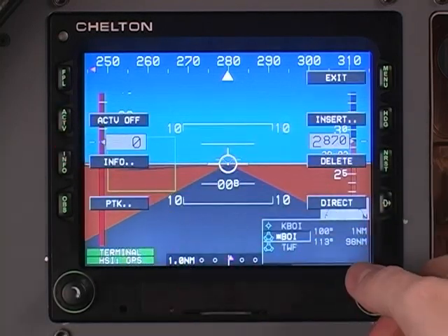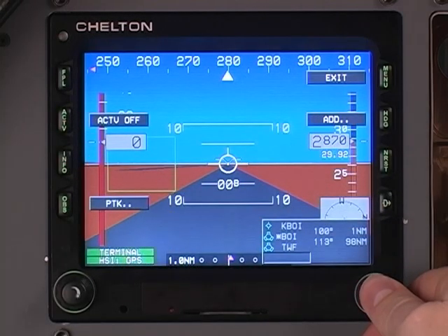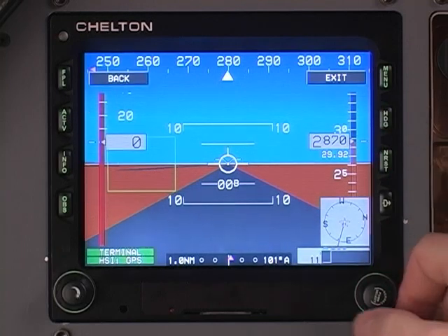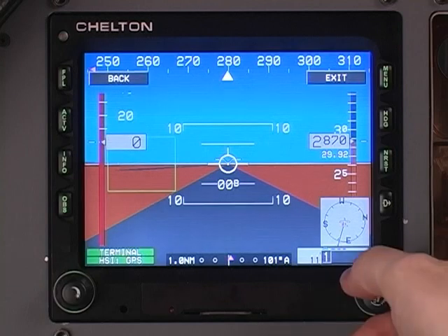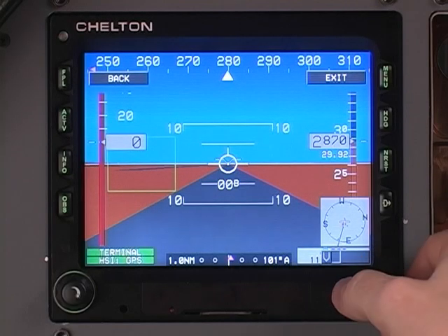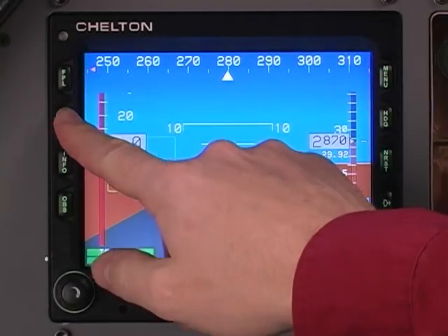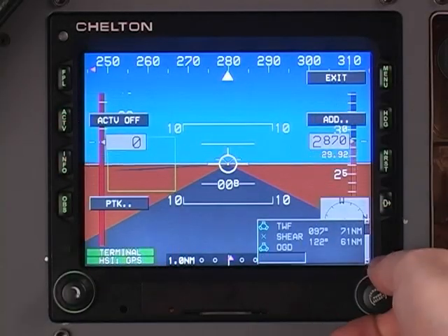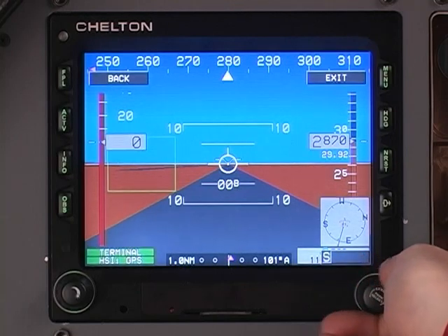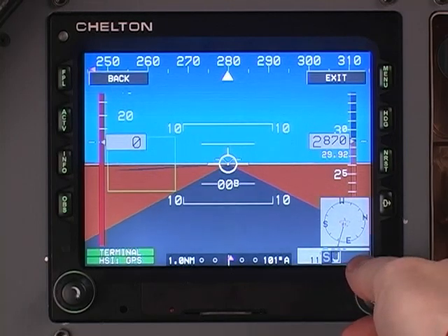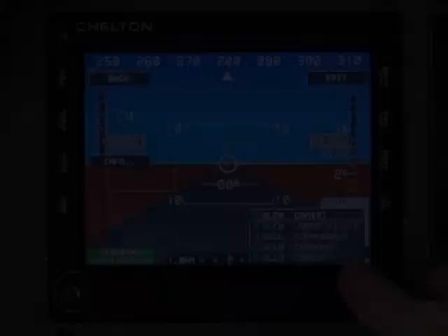The airway route will be drawn using VORs and turning fixes. Other fixes along the airways are eliminated to simplify the active route. Finally, use the same procedure to add Salt Lake City as the destination. Push Active, scroll to the end of the waypoint list, press Add, enter KSLC, and push to enter. Jet routes are entered the same way by using a J instead of a V.